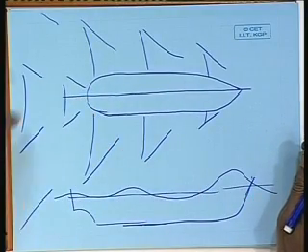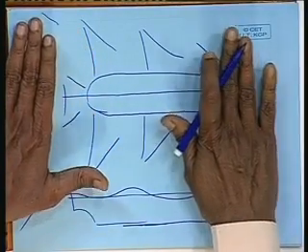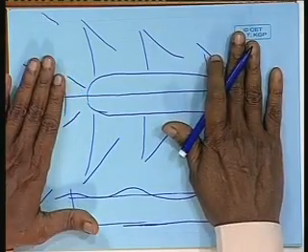Okay. So, from here you will find that there are two sets of waves, one at the forward end, one at the after end being generated. Now, what is so unique about the forward and the aft end? Why is there a high pressure point in the forward end and a high pressure point in the aft end? Because of a large slope at the forward end.